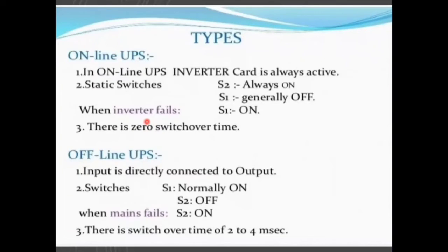Okay. Then offline UPS. Here also, the major part first: online UPS advantages, that is, the output of the inverter can be controlled. Next, voltage regulation is also better. That is the advantages of online UPS. And disadvantages: online UPS is very costlier than other UPS systems. Then the overall efficiency of the UPS is reduced since the inverter is always on.